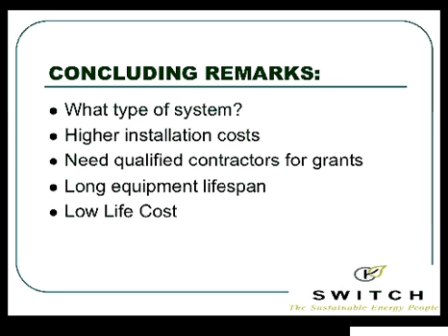And what that allows is a wider temperature operating window, for one, because now if I can slow down that outside fan, I can control it more, and I can run it at a lower outdoor air temperature than before. Before, we had to shut it off and go to our backup switch on our air source heat pump at, say, 0 degrees. Now I can run down into minus 20, minus 30 degree conditions because I can vary the speed of the compressor and the fan. So that means that coefficient of performance, and that's how we talk about heat pumps, that COP is higher, right?